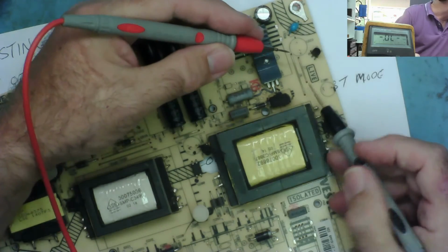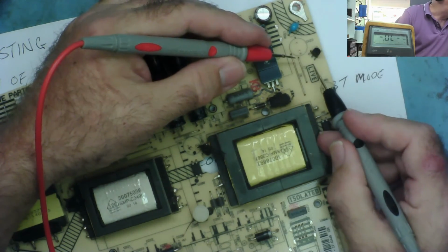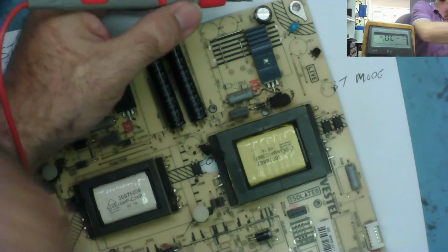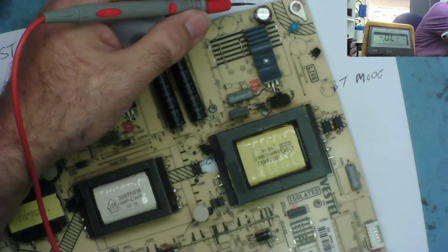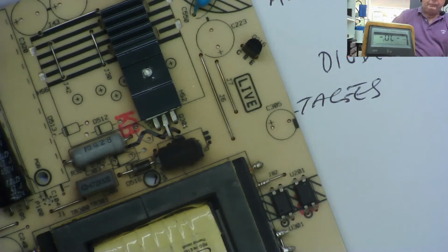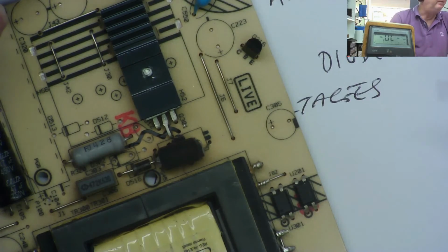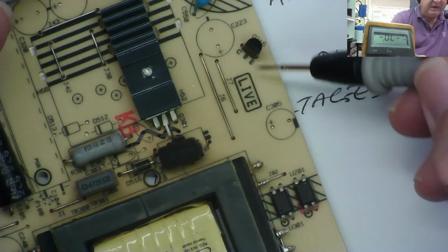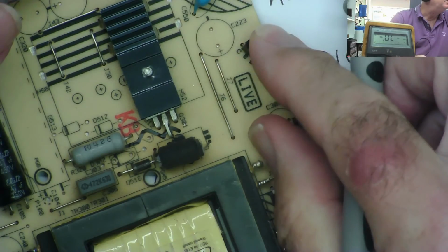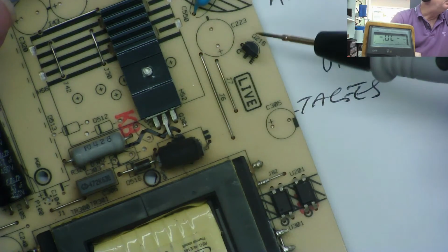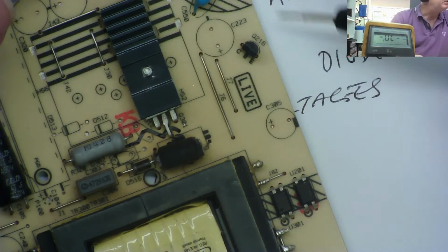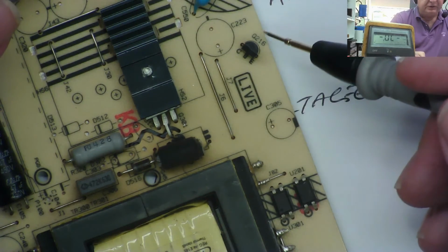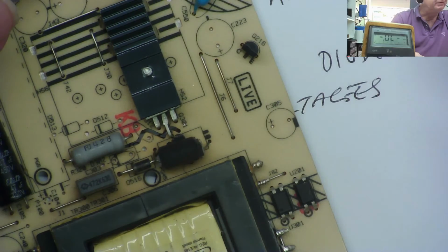Okay, here's a transistor. It's actually marked, if you can see on the circuit, CBE. Let me see if I can get a little bit closer on that. Are we on full magnification? Yeah, full magnification now. So this is a transistor. It's marked CBE, collector base emitter, so we know it's a transistor. On the board it's marked Q216. Q is commonly used for transistors. So if you see Q something or other, it is often a transistor.